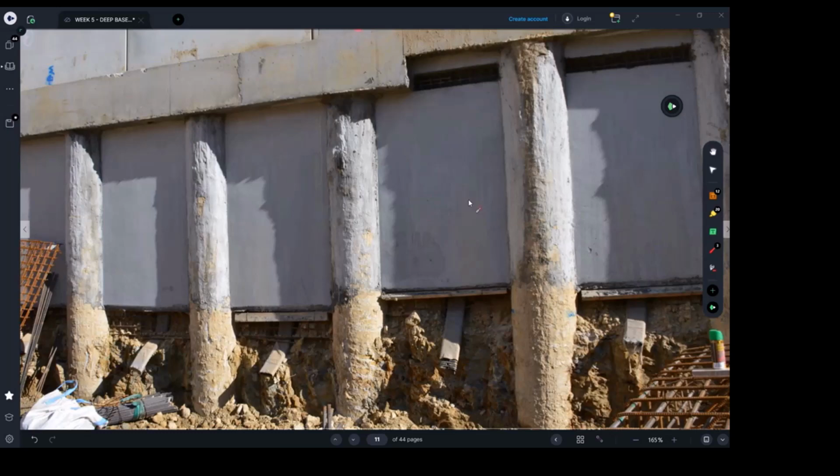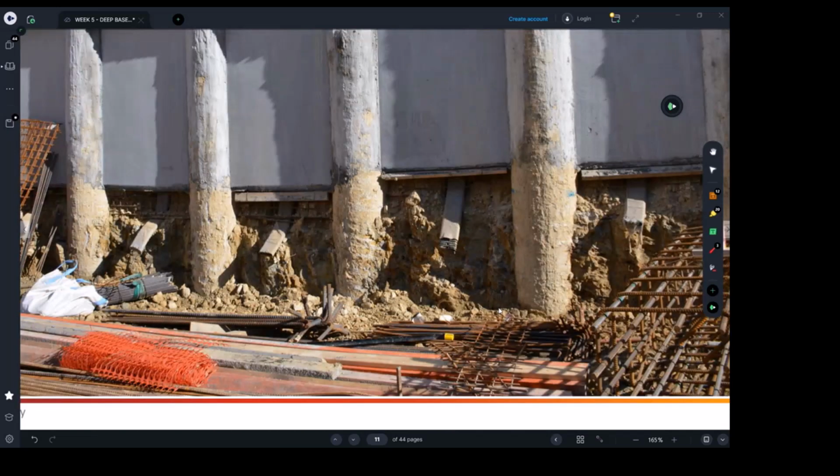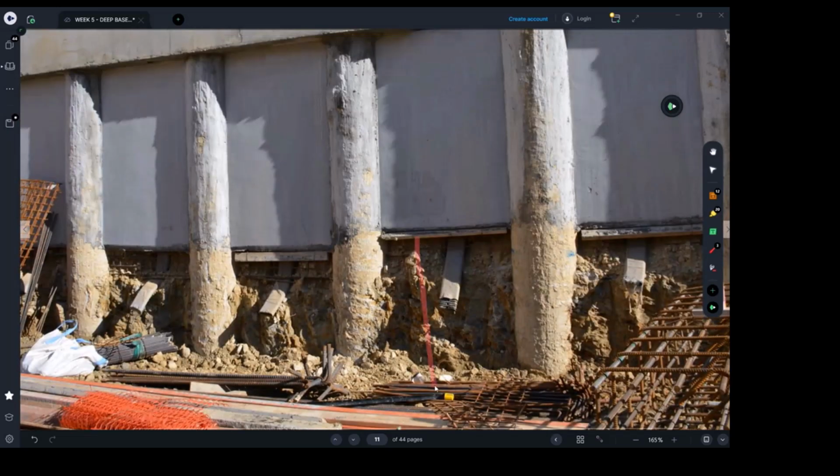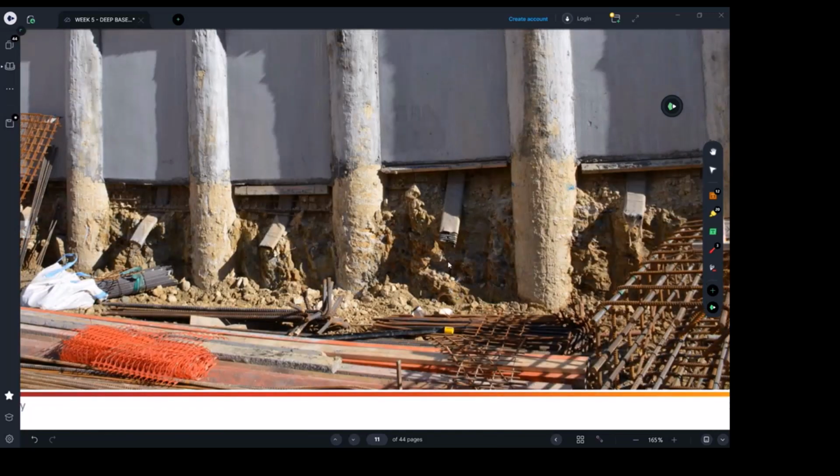They do this because they want to make sure they're going to stabilize the soil behind. They can't go all the way those 4 meters, whatever it was deep, because it may be unstable. All right, so now they're going to excavate for the other 1.5 meters or whatever it was possible. And if yes, they're going to connect more.